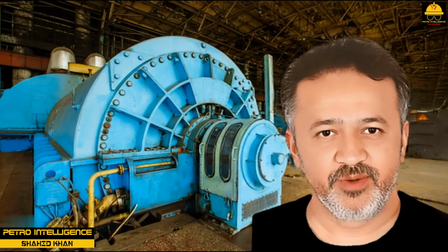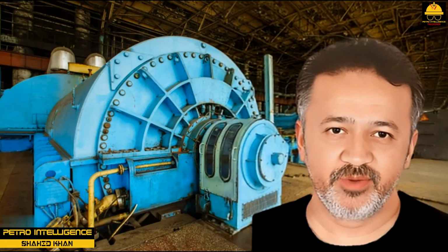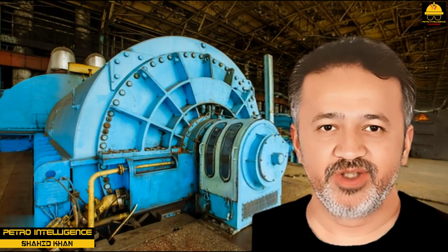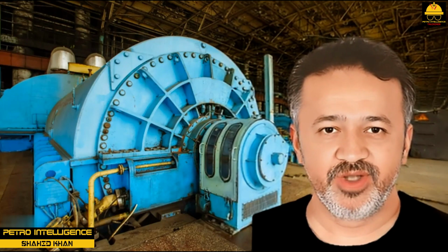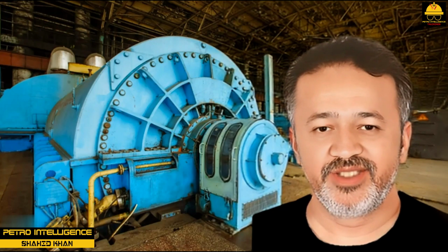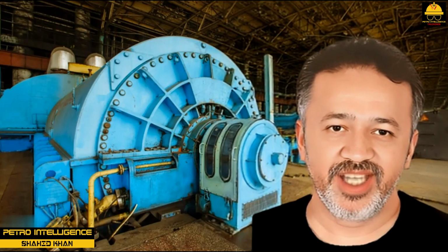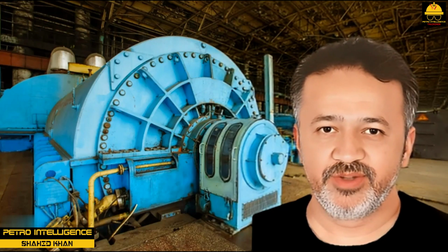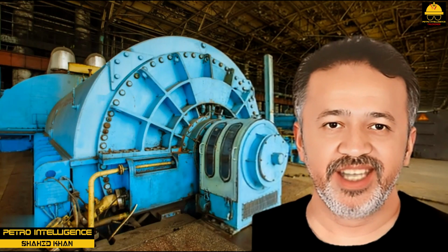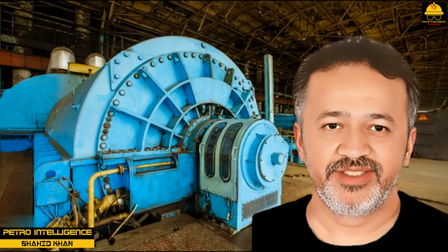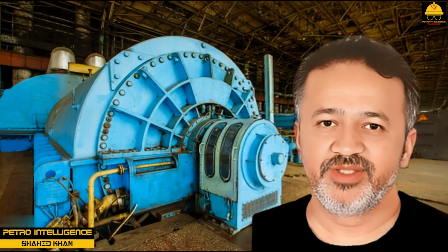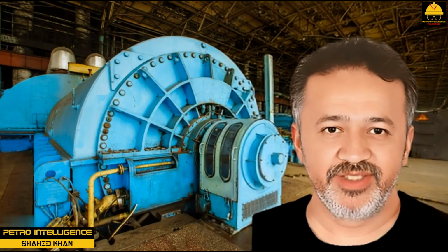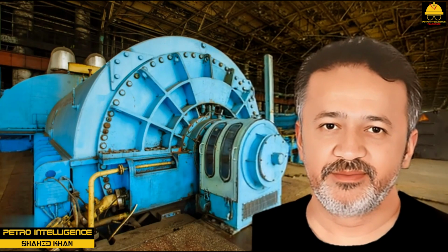A gas turbine uses high-pressure combustion to turn a series of turbine wheels to provide rotational energy to a driven device, in the same way a steam turbine uses steam to turn the rotor. The gas turbine system mixes compressed air with fuel in a combustion chamber. A spark plug ignites the mixture, which is directed into the suction side of the gas turbine. The hot combustion gases rush into the gas turbine, causing the turbine wheels to turn.